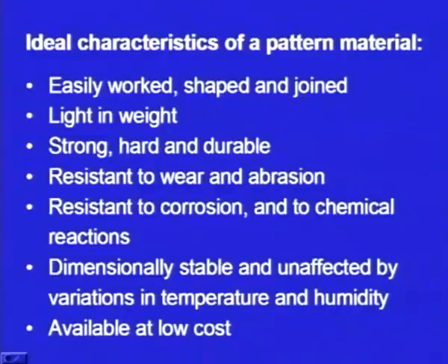When we make a pattern, it has to serve as the pattern for several castings. So that is the objective. So when we make a pattern, especially with wood and metal or alloys, they serve as pattern for making several molds, and it should be resistant to wear and abrasion. So this is very important.